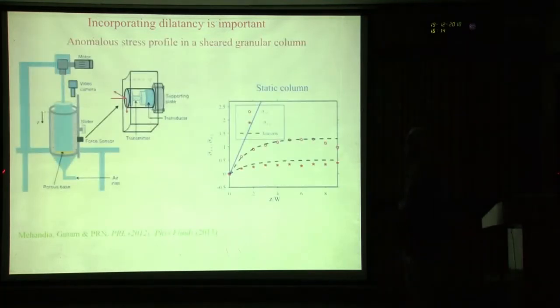The experiment was a rheological measurement of, say, glass beads in a cylindrical cuvette device, but by measuring the stress as a function of position. We could measure all components of the traction on the outer cylinder as a function of depth from the free surface.